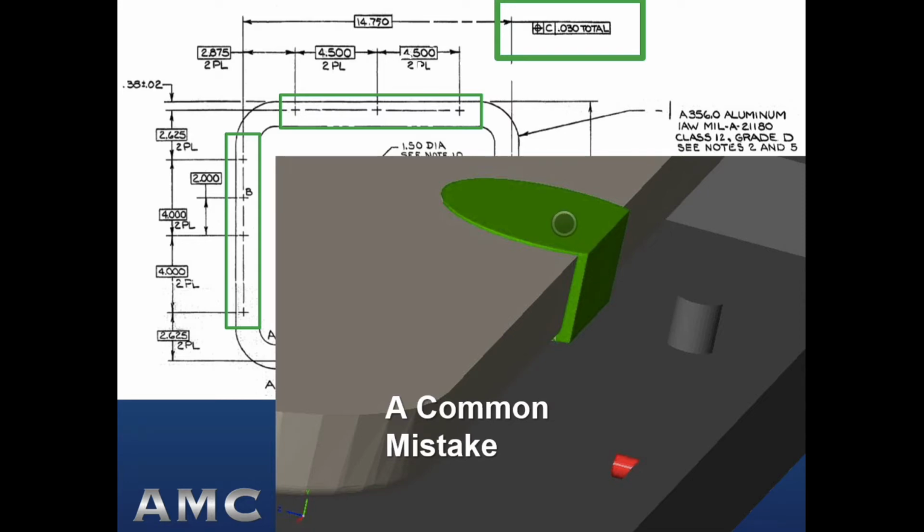But here's the issue. If the target touches one of these stubs that has been ground and processed, then we are likely to violate this 30 thousandths total wide zone for the position of the drilled holes on the machined face opposite of datum A. So all of the tolerance that we are shooting for hole position can be violated simply by targeting against a surface that has been cut off and ground like this.